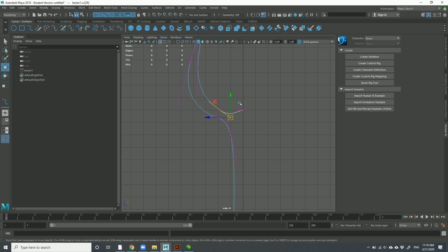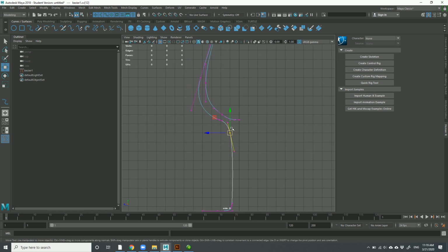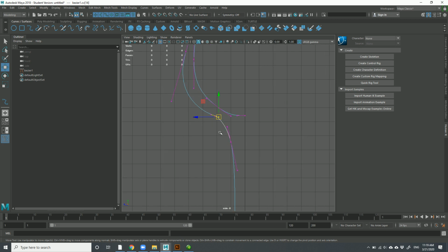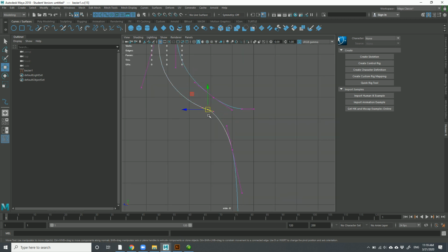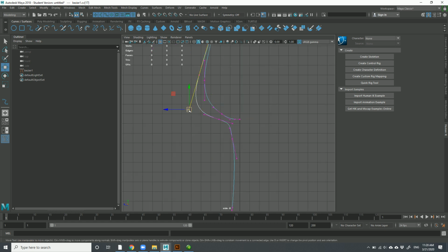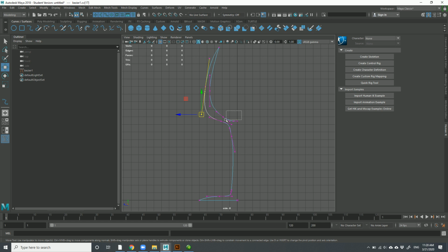So what I could even do here is just take this, and then maybe just take that, and that's more like the shape I was looking for here. And I can just adjust that here, just to keep it nice. I'm going to modify this here. Let's take that little point here. Again, I'm holding down Shift, right-click, and Bezier corner. And now I can pull this shape here more into that here. There we are.